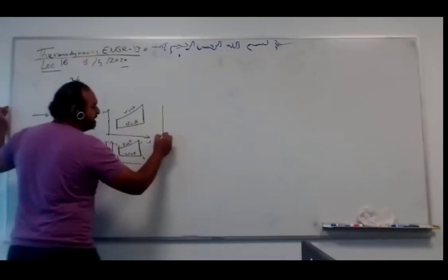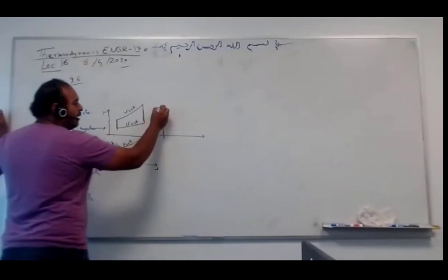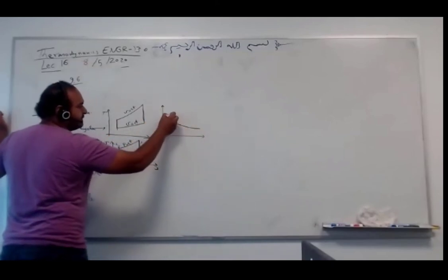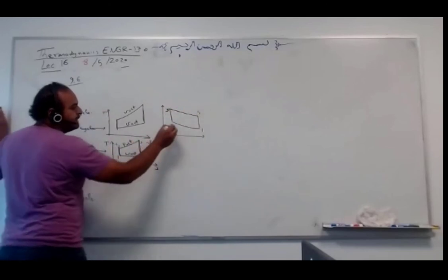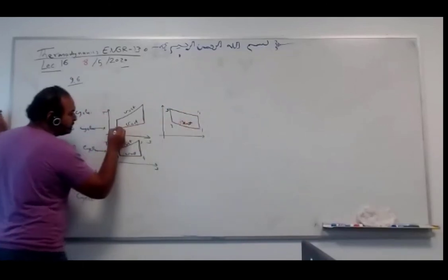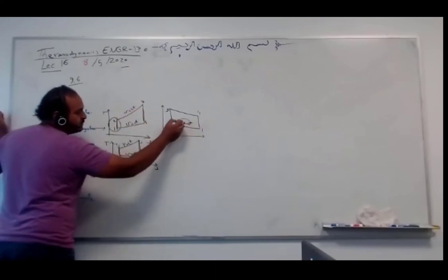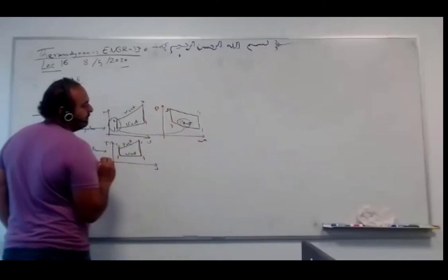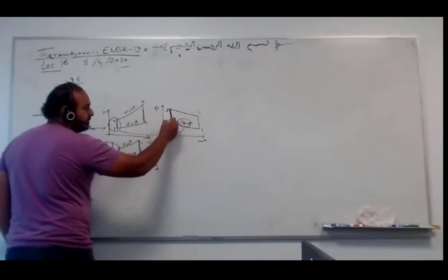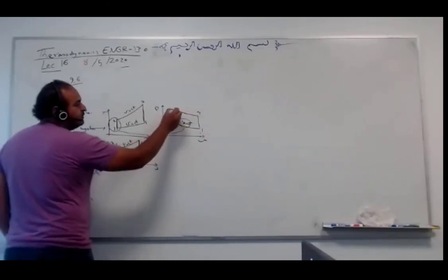If you go to the PV diagram, this is Otto, this is diesel. Otto is different, something like this. 1, 2, 3, 4. Here is opposite. I need to mention this is isentropic. Here I need to mention isentropic because it's a PV diagram. I do not need to mention this because it's vertical. I need to mention this.